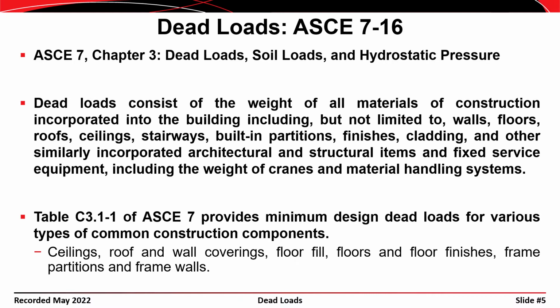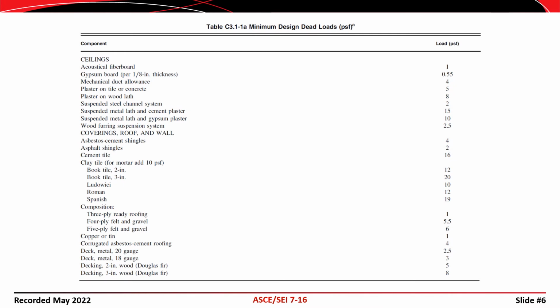In fact, there's a table, Table C3-1, that provides the various design dead loads you would use for various types of construction, different construction components. This shows an excerpt of that table. The actual table itself is several pages long, and I'll include it in the PDF version of this presentation that's posted online.